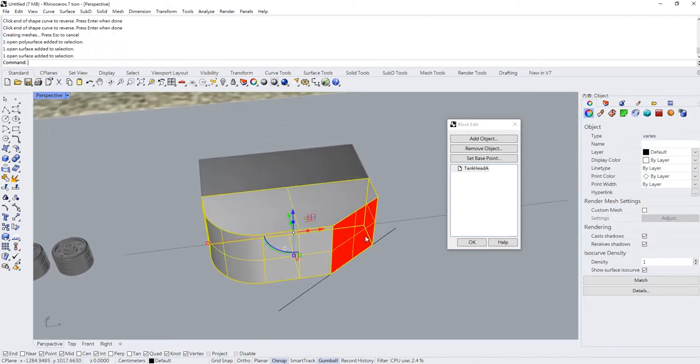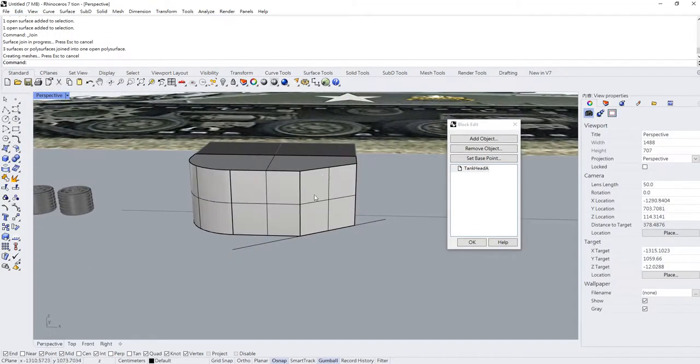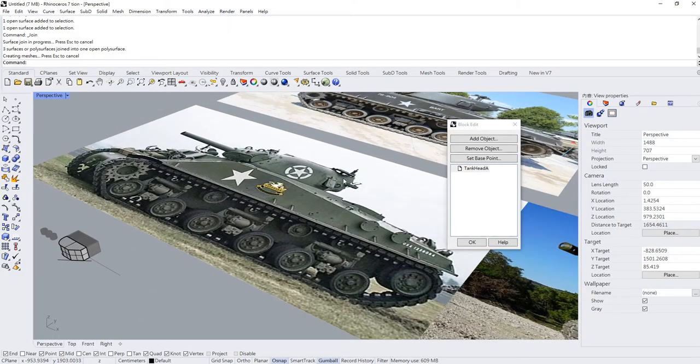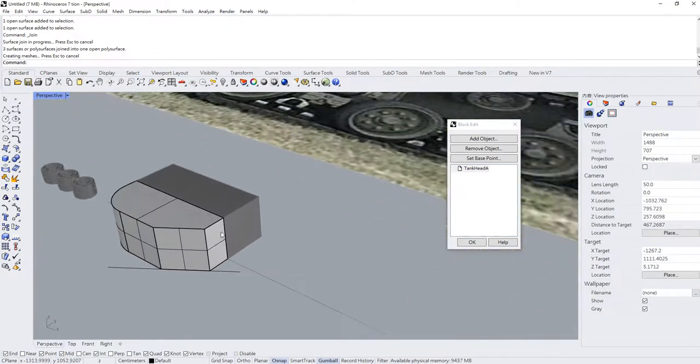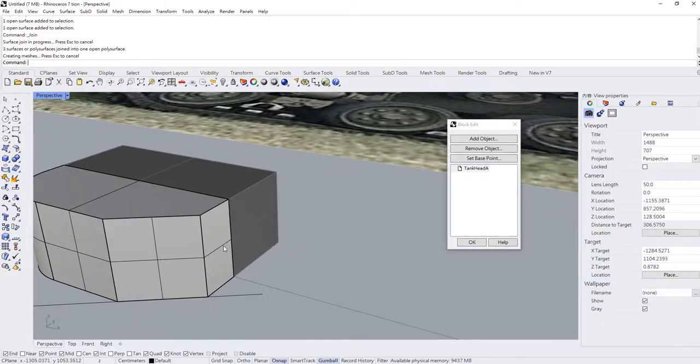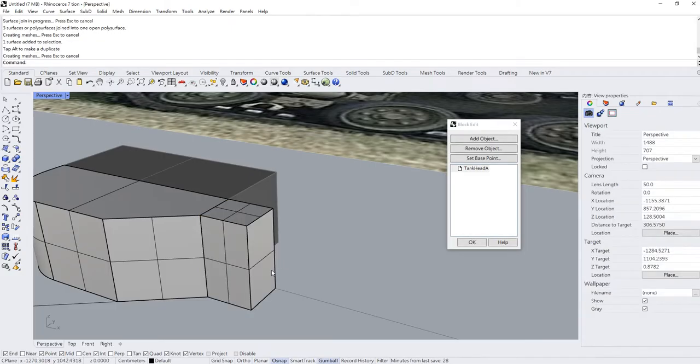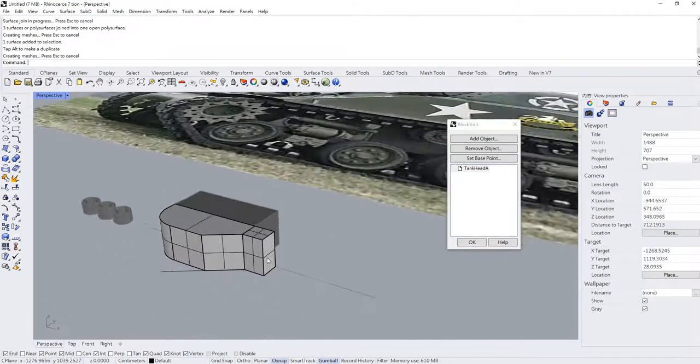Finally, select all of them and press Ctrl J for join or go to edit, choosing join. Alright, so next part I want to create the big face, this area. So how can we do that? Very easy. Choosing Shift and Control key, select the face here, and choosing Extrude for extrusion. I'd like to extrude probably, well, it doesn't matter. It's up to you. Just visually okay, and you will be fine.